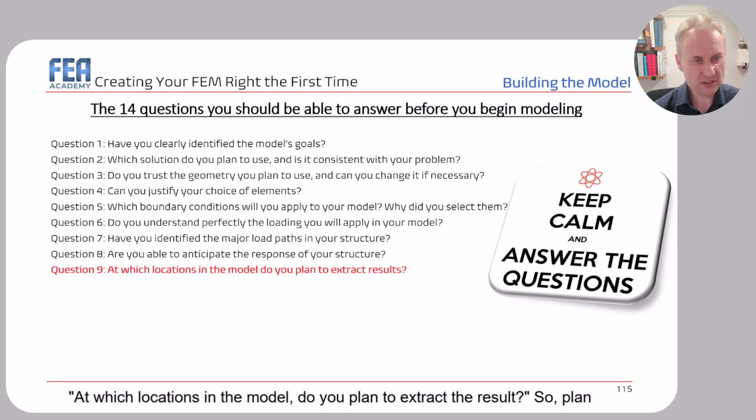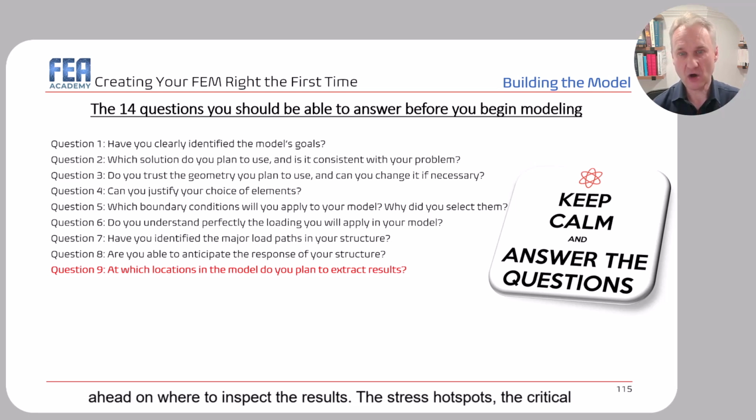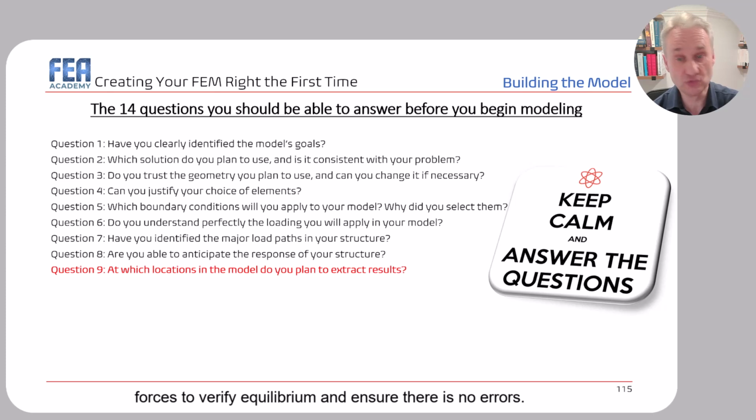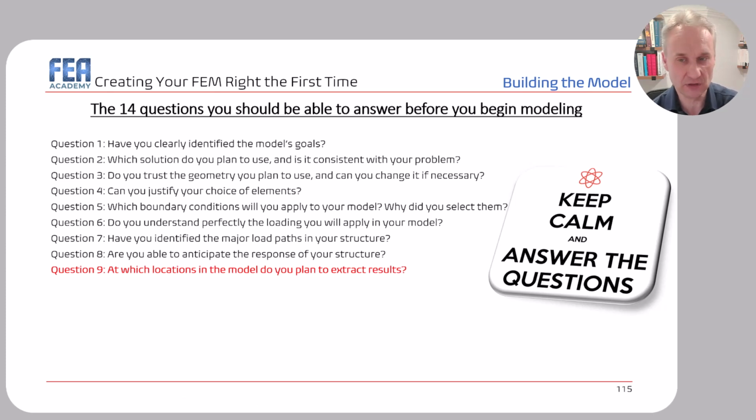At which locations in the model do you plan to extract the results? So plan ahead on where to inspect the results. So the stress hotspots, the critical deformations, the critical zones like the high stress regions, and the reaction forces to verify equilibrium and ensure there is no error in how you constrain the model.